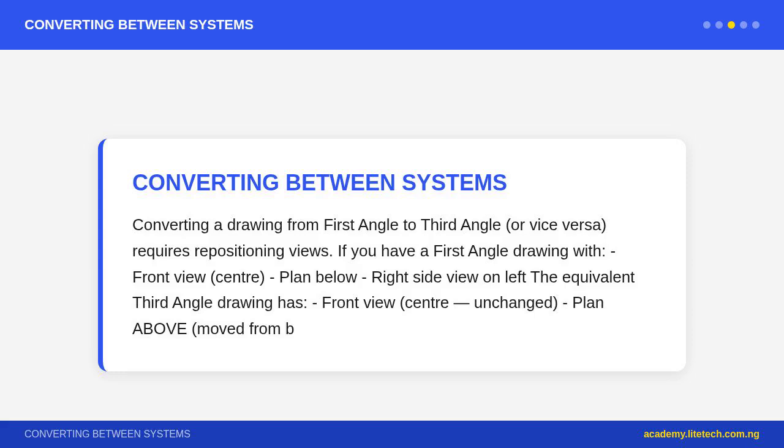Drawing 3 views of a step block, practical worked example. Object description: a rectangular block 60 mm x 40 mm x 30 mm, L times W times H, with a step cut. The top right quarter of the front face is removed to a depth of 20 mm and height of 15 mm. Third angle views. Front view, rectangle 60 by 30 mm with a notch in the top right corner, 20 mm wide, 15 mm deep.